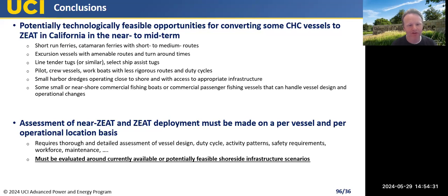You have to do a thorough and detailed assessment of the vessel design, its duty cycle, how it's used, what the safety requirements are, what the workforce is like, and how you maintain it. And then, really important, you have to evaluate the opportunity around available or potentially feasible shoreside infrastructure scenarios. You can't understand if the vessel is going to work until you understand the shoreside infrastructure.